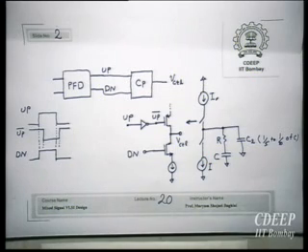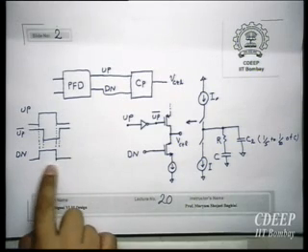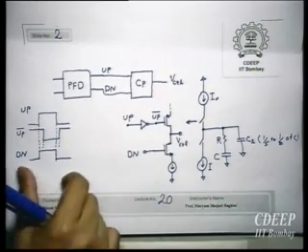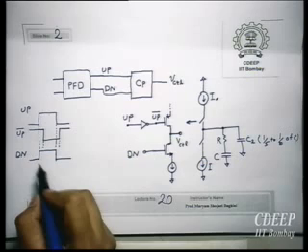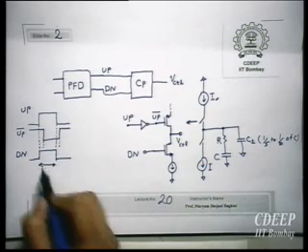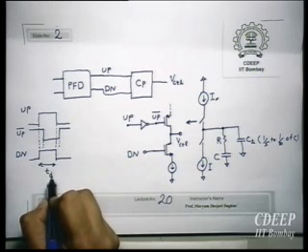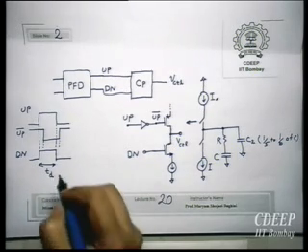The reason is because of the inherent delay of the pulse frequency detector, there will be narrow pulses. I have extended this narrow pulse, I'm just showing it wider, because this will be more than the delay of one inverter. So this is the width of that narrow pulse. I call it TD.